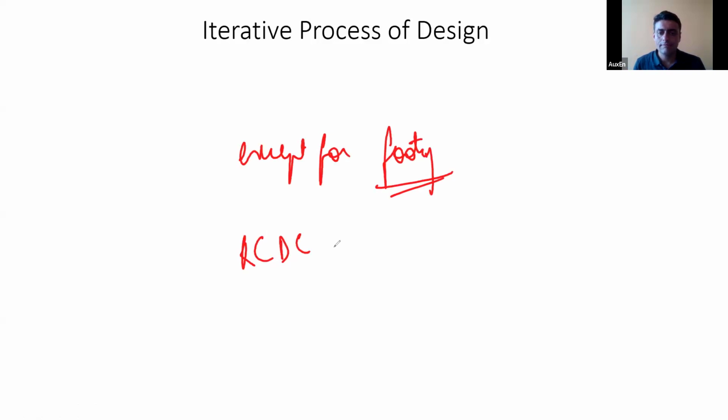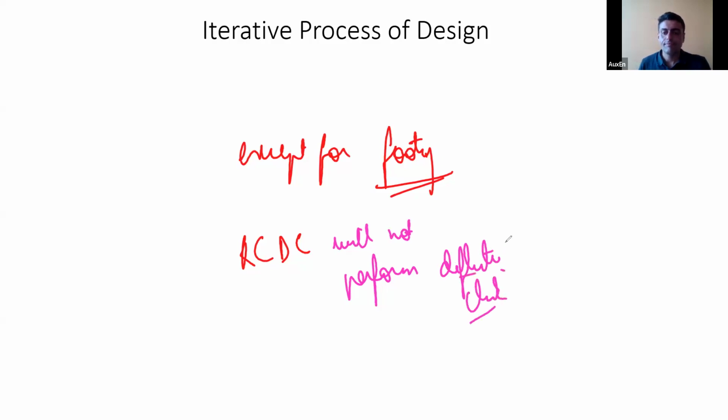Cracking it will do, of course. Deflection checks it will not perform. Are you clear with this? So if you want to perform deflection checks, etc., you do it in your STAAD file or ETABS file itself. Don't rely on RCDC for that. Clear?